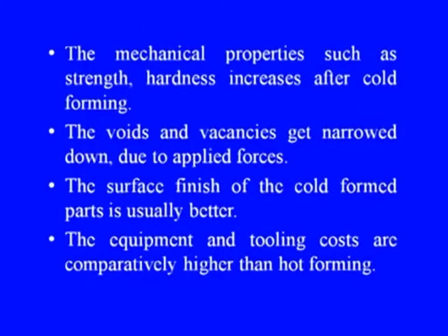The voids and vacancies get narrowed due to applied forces. The surface finish of the cold formed parts is usually better. The equipment and tooling costs in cold working are comparatively higher than hot forming.